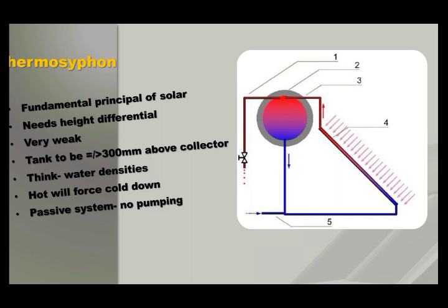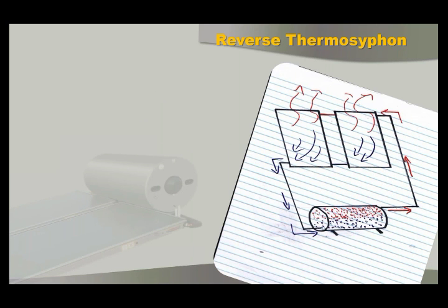So now, for a thermosiphon system, if you put a stop tap, a rough brass stop tap on there, what I described a couple of slides ago is exactly the kind of thing that will stall a system as well. So even though it is a stop tap in a fully open position, and even if it's facing the right way, it's too risky to put in there. It's got to be a full bore angle lever ball valve.